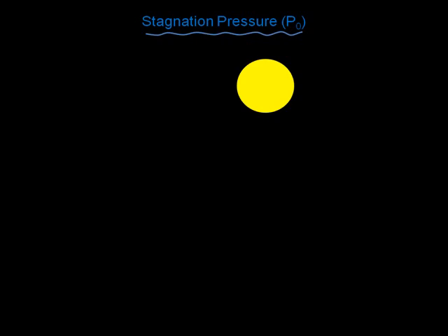Let's talk about stagnation pressure. I kind of cursorily went over it and said, hey, that's where the velocity comes to 0 rapidly and isentropically. But let's see how it could be useful. So let me draw that cylinder again. And again, it's a cylinder going into your screen. I'm not going to draw all the streamlines. I'm just going to draw that streamline that goes straight into the front and crashes right into the front of that cylinder. So if I label where I began as pressure 1, velocity 1, and elevation 1,